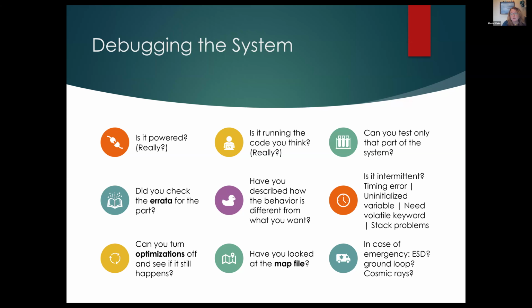The hardware abstraction layer is the very lowest layer. It covers the hardware so that ideally you can change between processors, but realistically, it just covers the very lowest level so that you can say, turn on port A pin 7 instead of writing to a horrible address or even writing to a structure. So the HAL is at the very bottom. The middleware are the libraries and things that use the HAL, but also add features to it and are primarily software-based. And firmware is the whole thing.